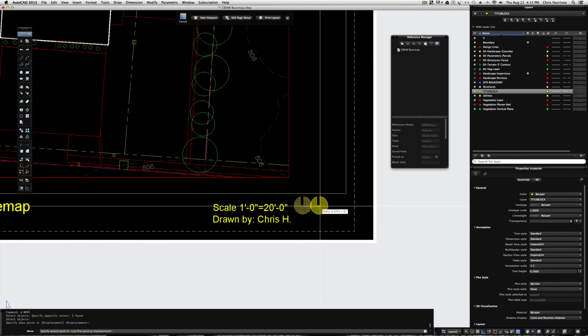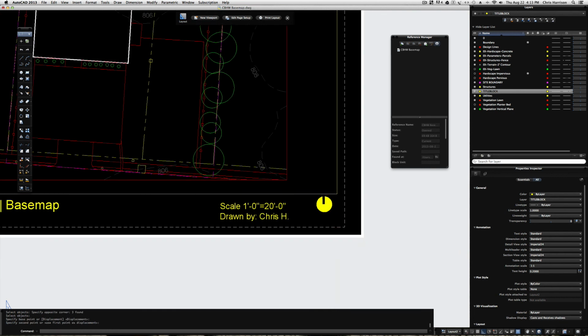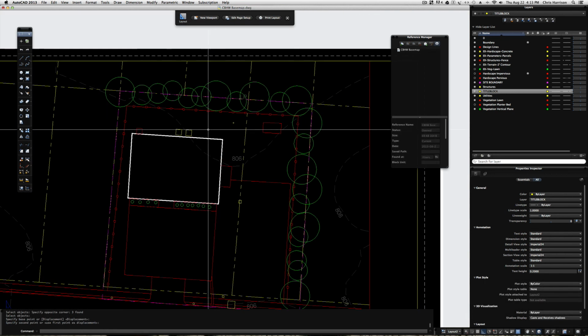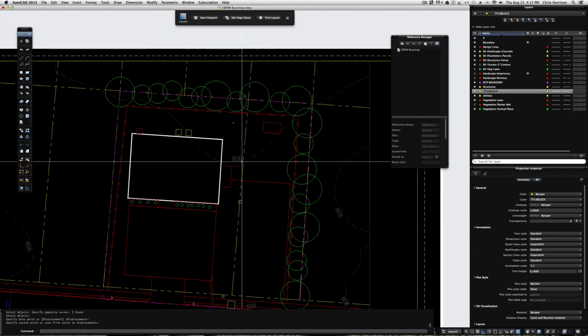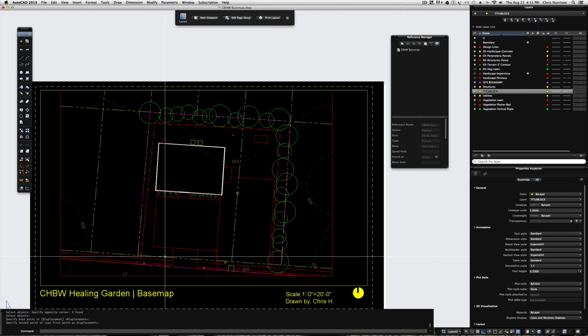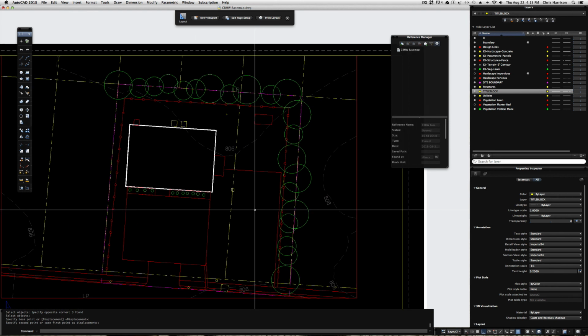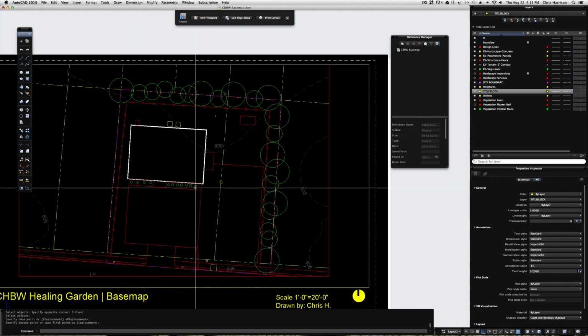I'm just going to move this over a little bit. And you can use this base map now to help orient yourself, and also you would need to identify what these items are. They're here, they're spaces, but what are they? And we'll pretend like in this particular survey that information wasn't given to you. If it's a good survey, that should be there. So you need to identify some of these things and begin to record this on your base map.